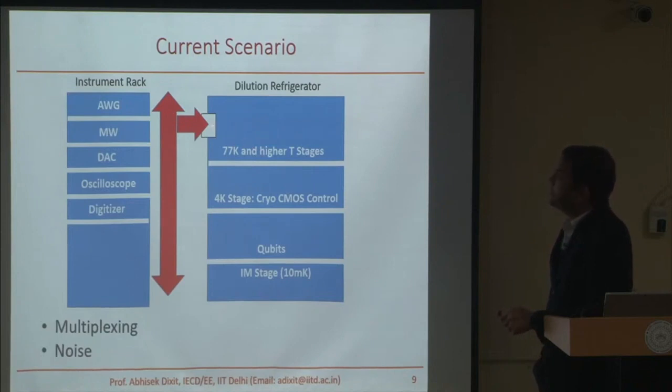But if you want to do that switching from here to here, instead of two cables going from here to here, you will have 48 cables going all the way up here. So thermal load will immensely increase. That's the reason you need that adapter and sample PCB.